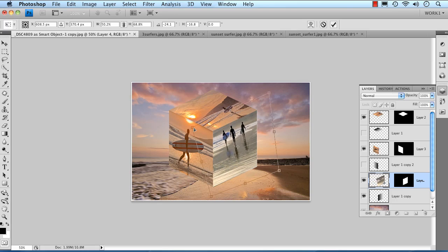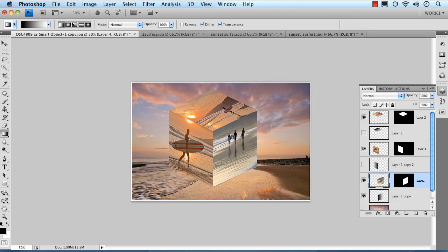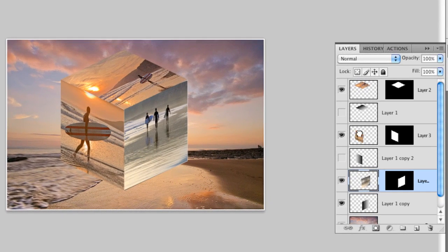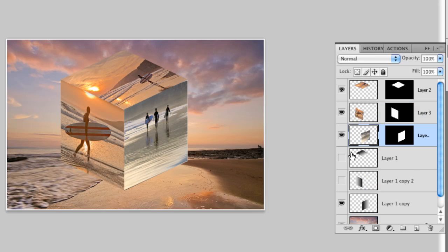So we can now lift this around like that, popping that into the corner, dragging that one down, and that one down like this, and just lifting those around until we get it sort of, you want to keep that square look as if you are looking at the edge of a block like that. That is important. That's why the Distort tool works so well. So bringing it in, bringing that in, and once you're happy, press enter or return. Job done. Right, now what we can do is we can lift these up together. So picking on this layer here, lifting it up, dropping it underneath, lifting this image layer up, popping that underneath. That's leaving us with these three for our block.